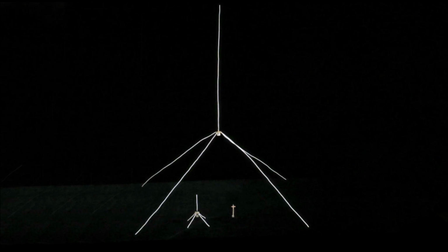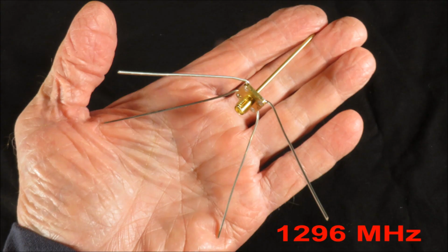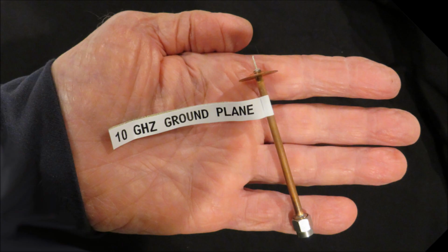The length of the vertical quarter wave element is critical. The number and lengths of the surrounding wires or rods that form the ground plane are not critical, but should be at least a quarter wavelength long. A disc of metal makes an excellent ground plane. There are ground plane antenna calculators online that you can use to get the needed dimensions. If the radials are bent down at an angle, the antenna will present a much better match to common 50 ohm coax feed line. Some call the quarter wave ground plane an omnidirectional antenna, meaning that it radiates equally in all directions, which we will see is not at all true.